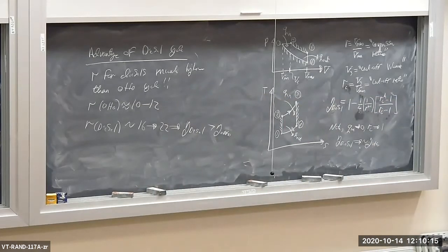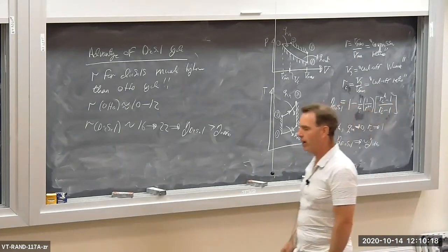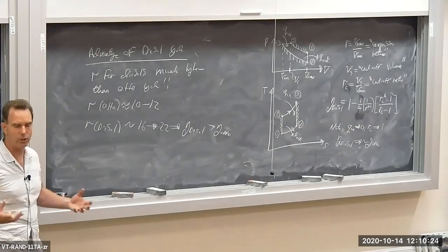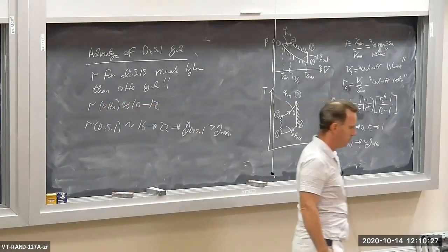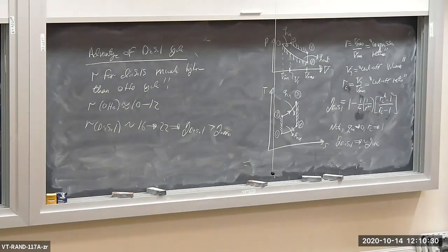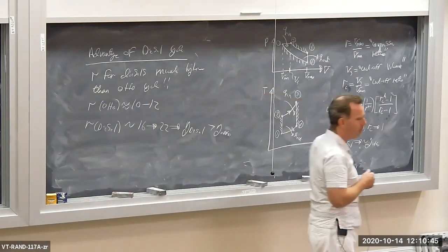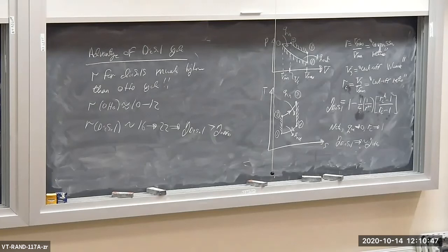You can't get too high or you start having mechanical problems. You'll end up getting very high friction. You have very high compression ratios and pressures, so you have to make the engines very bulky and heavy to withstand the forces associated with those high compression ratios and high pressures. Okay, so the primary advantage of the diesel is we can have higher compression ratios and therefore higher thermal efficiencies for the diesel cycle. A good diesel cycle will probably get around 30 to 40% thermal efficiency. A good Otto cycle will probably get around 20 to 30, maybe 30.